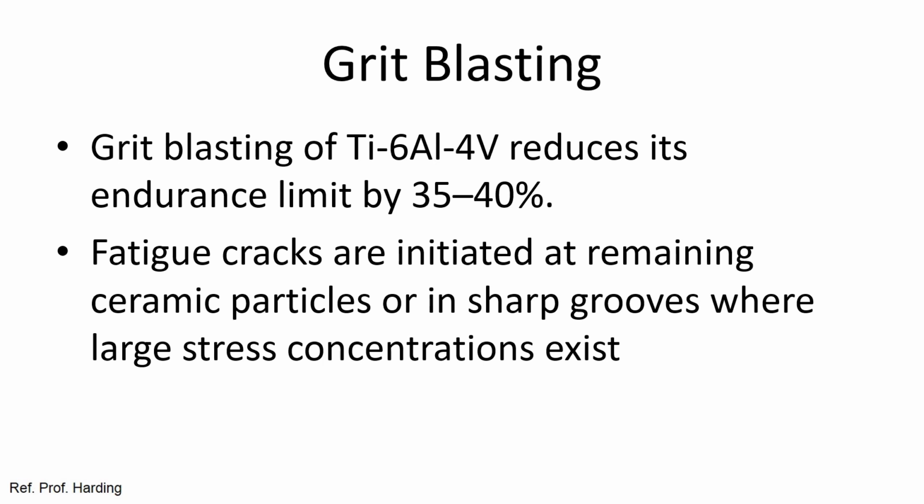Fatigue cracks are initiated at remaining ceramic particles or in the sharp grooves where large stress concentrations exist. Basically, particles are left behind from the grit blasting process. Small particles are left embedded in the surface of your implant. Depending on the cleaning protocols, the size of the particle, and the pressure used to produce the blasting, these all influence the effect they have on the endurance limit.